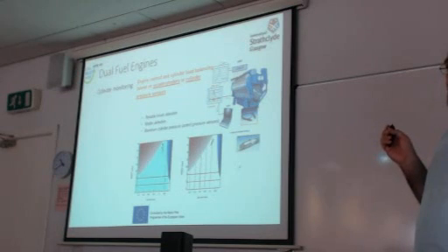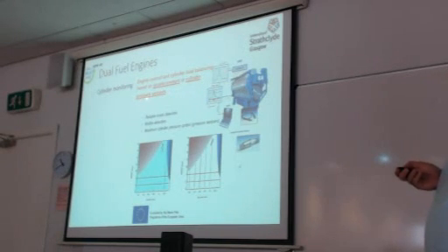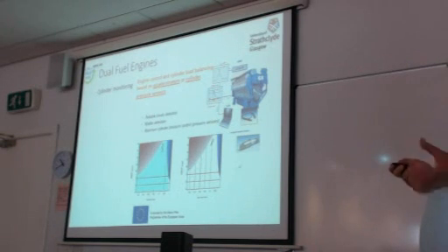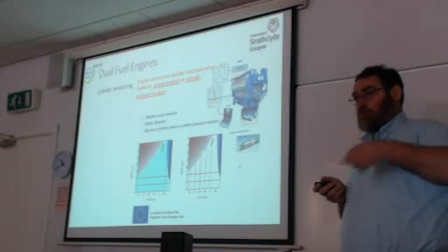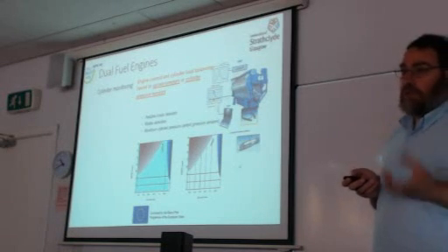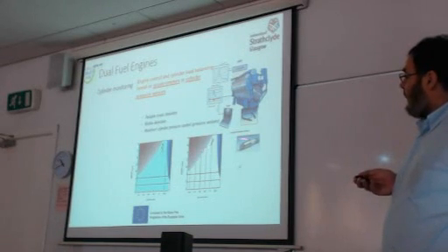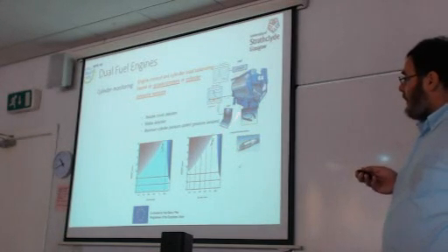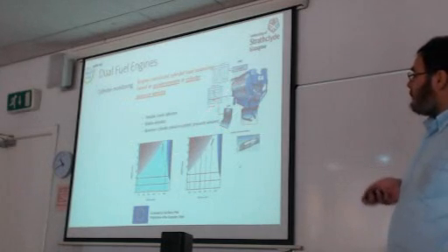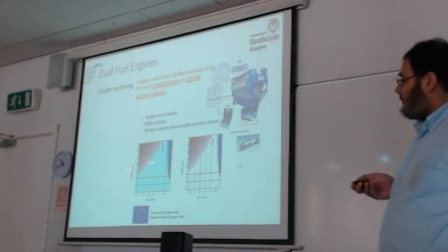So another important thing to remember is that the engine should always be monitored, because knocking can cause severe problems in the engine. In this case, what is needed is accelerometers and pressure sensors, and of course the pressure diagrams are recorded and analyzed. Knocking affects the pressure level and pressure variation, and pressure variation produces vibrations and can be detected by measuring acceleration.